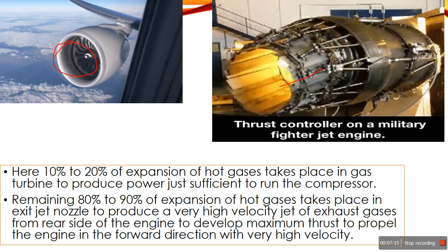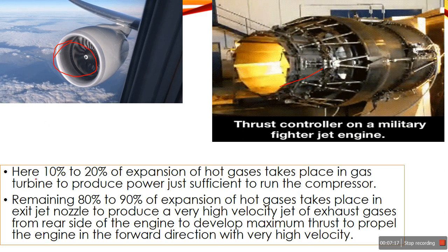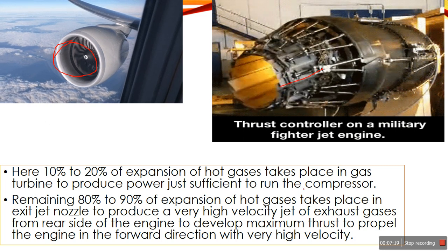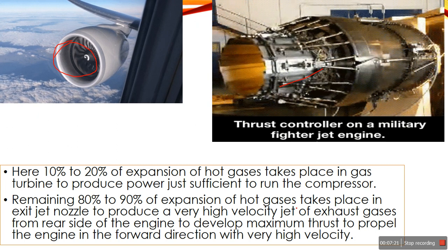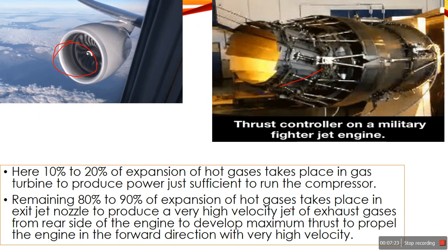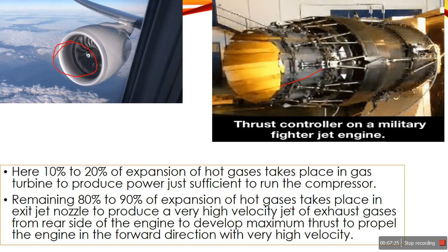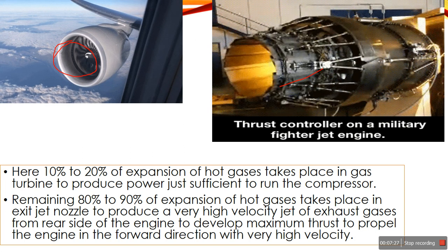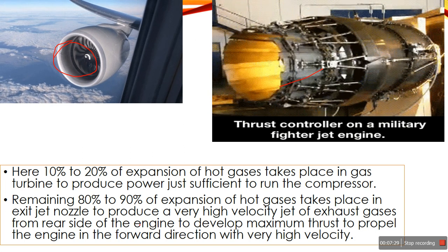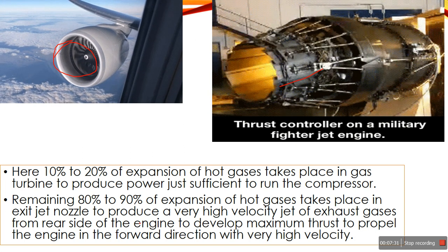Here, 10 to 20% of the expansion of hot gases takes place in the gas turbine to produce power just sufficient to run the compressor. The remaining 80% to 90% of the expansion of hot gas takes place in the exhaust nozzle. I will also discuss this. Okay, see the further applications also.